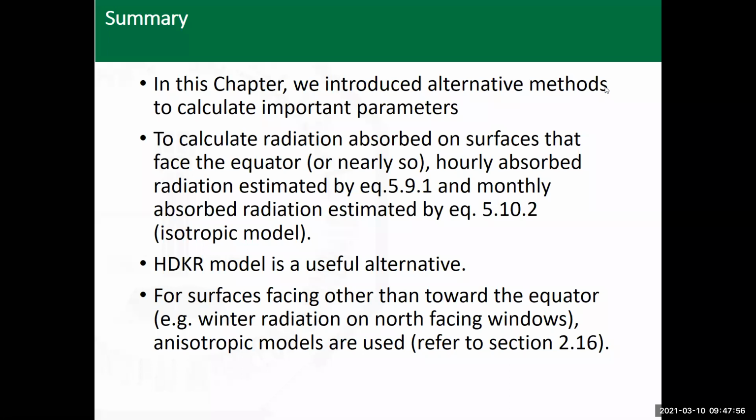Something slipped my mind when I was asking you the questions about the values of S. Why does S change? Because S is the energy absorbed by the solar collector or the surface, and definitely it will depend on whether we have single glazing or double glazing and so on.